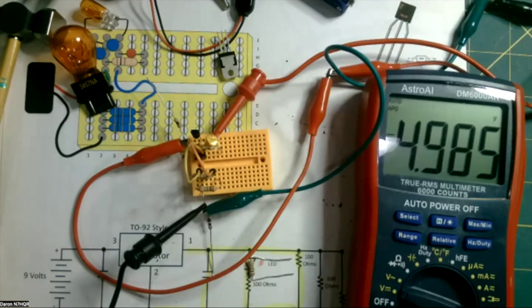And you can rejuvenate tubes that way. In fact, it used to be when you had picture tubes in TVs, when the tube would get worn out because it's been used for so long and the electrons aren't able to get out anymore, they had rejuvenators that would put a high voltage on the filament and draw electrons to the surface. And sometimes you can make the tube last a little while longer. Not too long.